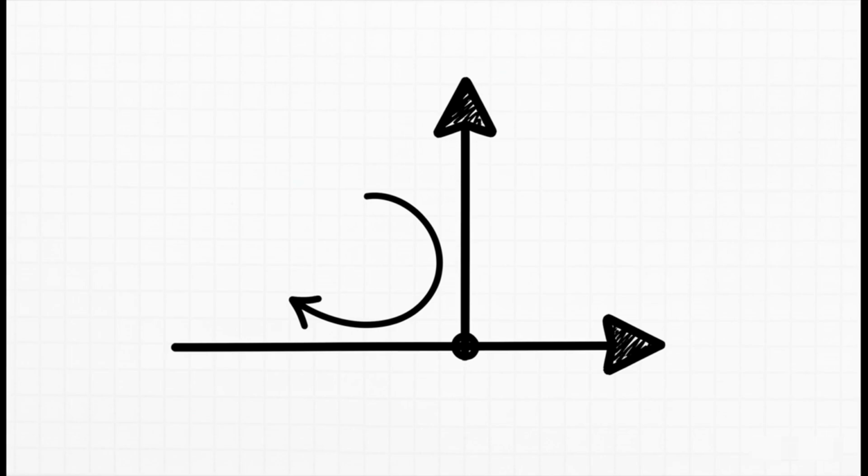So what does it actually mean for the voltage to lead on the phasor diagram? It means there's a specific gap between them, exactly 90 degrees. So if you picture the current phasor pointing straight to the right, the voltage phasor is already a quarter turn ahead, pointing straight up. With an inductor, the current is always lagging behind, playing catch-up.